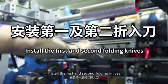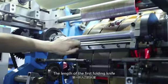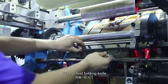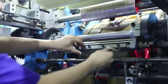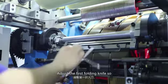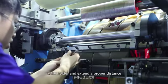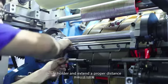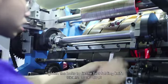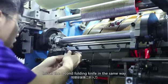Install the first and second folding knives. The length of the first folding knife is the width of the paper bag plus 2 to 5 mm. Put the first folding knife into the clamping plate of the knife holder. Adjust the first folding knife so that it is parallel to the knife holder and extends the proper distance. Tighten the bolts to fix the first folding knife. Install the second folding knife in the same way.